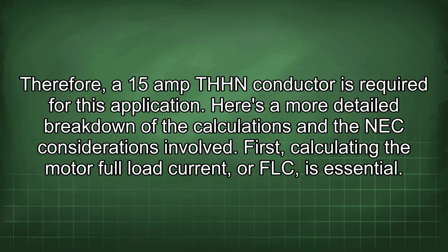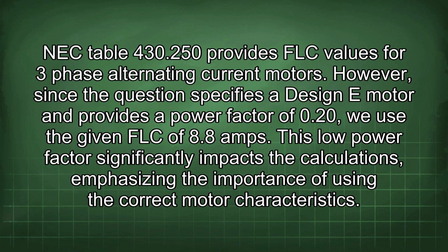Here's a more detailed breakdown of the calculations and the NEC considerations involved. First, calculating the motor full load current, or FLC, is essential. NEC Table 430.250 provides FLC values for 3-phase alternating current motors. However, since the question specifies a design E motor and provides a power factor of 0.20, we use the given FLC of 8.8 amps.